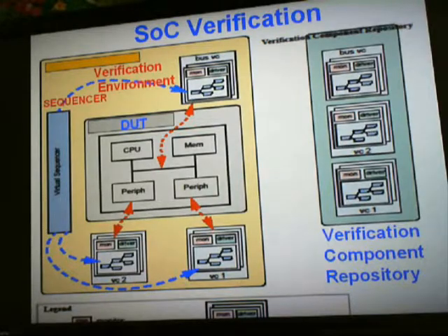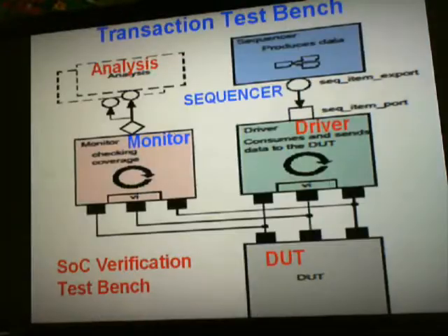The interface verification component is instantiated and configured for a desired operational mode. The verification environment also contains multi-channel sequence. It is a sequencer to synchronize timing and data. Data items represent the input to the device under test, the DUT. It includes networking packets, bus transactions, and instructions.